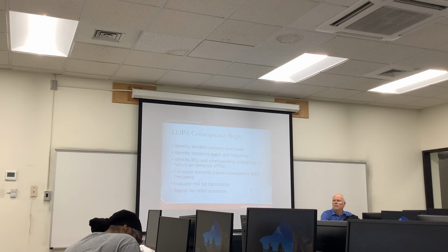Let me ask you, do shutdown systems have a probability of failure on demand, or do they just always work? Yeah, your initial idea would be, well, a shutdown system always works, right? Well, what if you have an unrevealed failure? Is it going to work then? No. Shutdown systems have a probability of failure on demand, and that probability of failure on demand depends on how often you test them. And you have to test them all the way to the final control element.